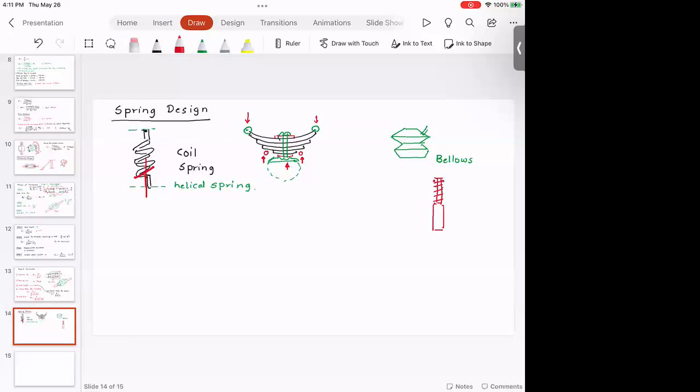So this is the absorber or shock, also called as strut. So if you see, it is something like this. I don't know if you work on cars, but if you want to change the strut, you will have to take the 3 bolts off of the chassis, and then there are 3 bolts off of the engine hood, and then you get the whole assembly out.